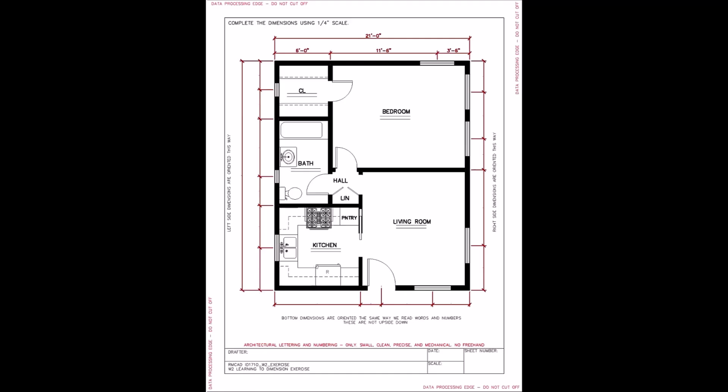So while the instructor may be telling you that you are drawing in an 1/8 of an inch scale or a 1/2 inch scale, hard as you might try, those printouts are not ever going to be accurate. And the best way to try and fix that is trial and error, of course, and then using your scale when you do print something out for the first time.